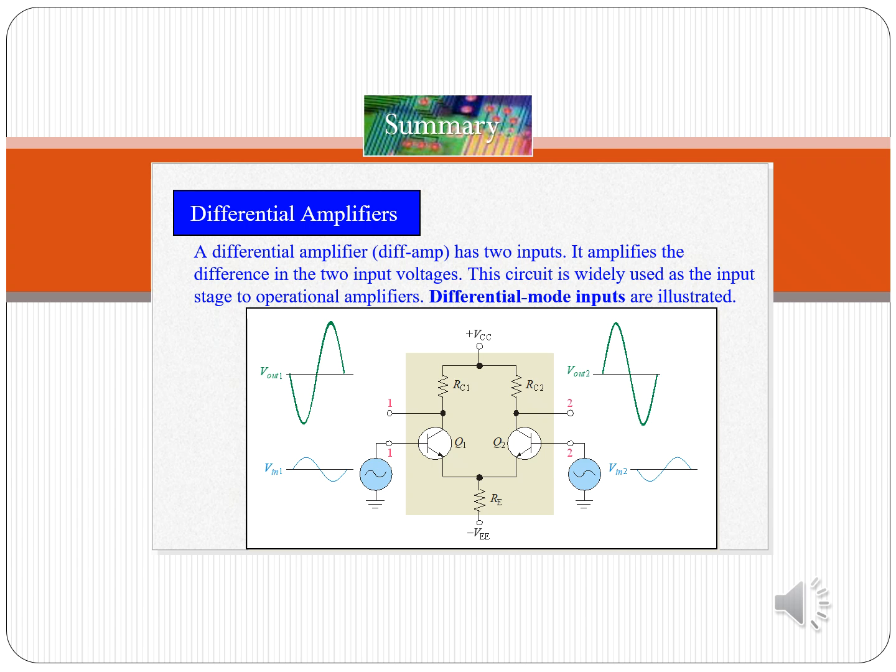Looking at the schematic, we can see that Q1 and Q2 share a common emitter resistor, R sub E. And so when V input 1 rises and V input 2 falls, current flows more through Q1 and less through Q2, causing opposite voltage swings at the collectors, so V out 1 and V out 2. But the big idea here is that this circuit is all about comparison. It says, I don't care about absolute voltage, I care about which side is stronger.